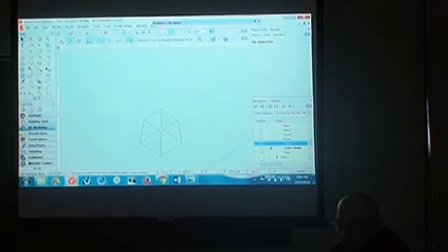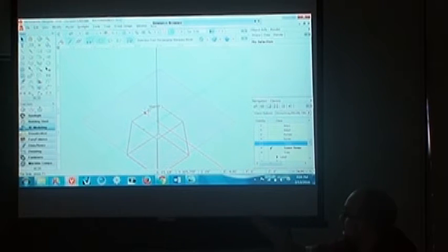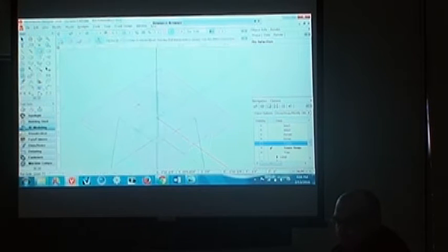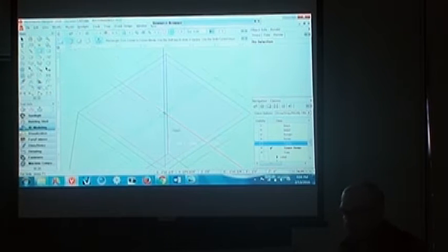I could go ahead and create a working plane right on this base footing if I want to. So I want to put a profile here of the leg. So I just use my facial selection set working plane mode to select the top of this footing, and I'm gonna draw from the center. I wanna draw.